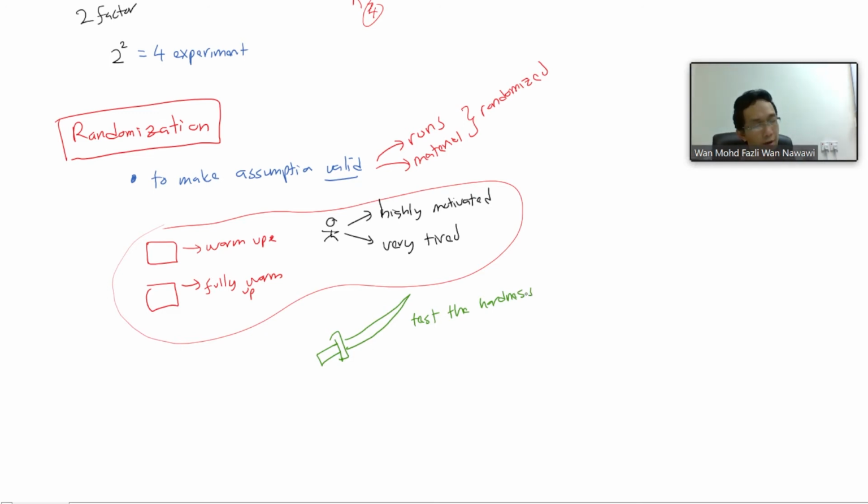So one factor that can affect this hardness is basically quenching. Basically you put this sword in some liquid. That's what it means by quenching. Quenching is basically you put this metal in the water. After you produce it, it's hot, and then straight away you put it in the water or in the oil. So the quenching here can be done either in water or in oil. Okay, let's say this experiment.